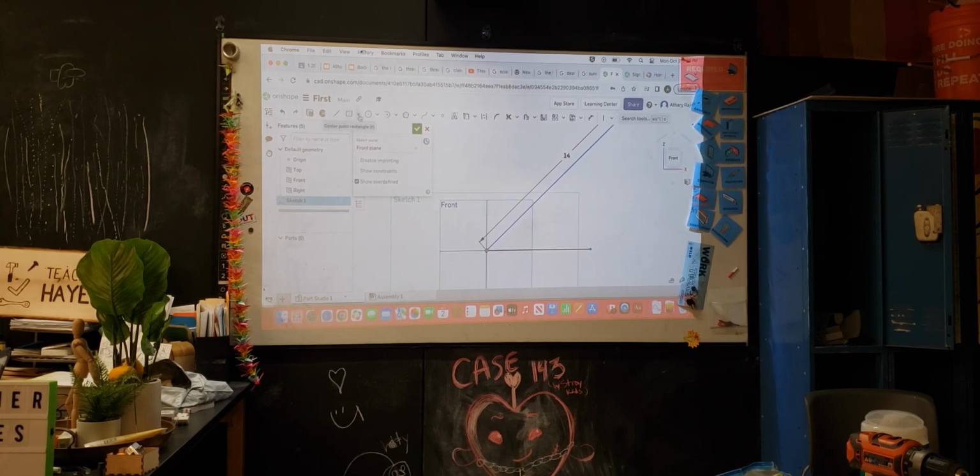But yeah. With the dimension tool, you can also make angles relative to other lines. So if you click a horizontal line and a line out in space, you can set an angle you want it to be at. So I wanted that to be 45. What I did is I went to the dimension tool, I clicked on one line, I clicked on the other line I want to set the angle to, and I set the angle to 45, or I wanted 60.